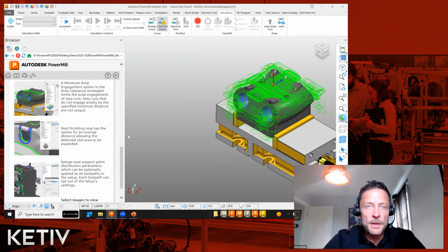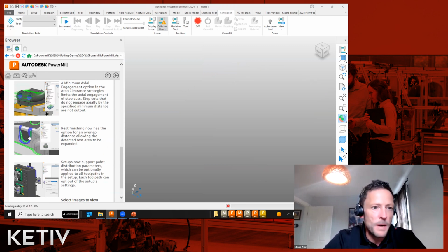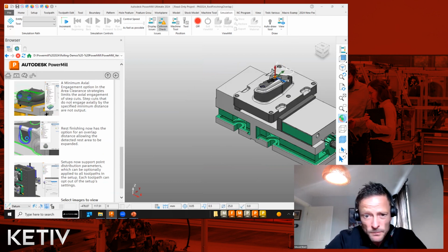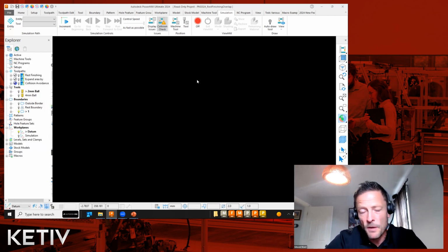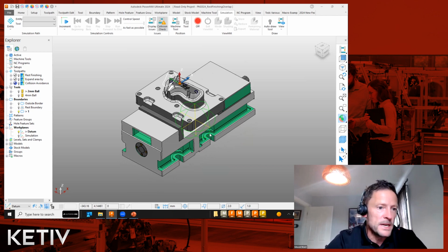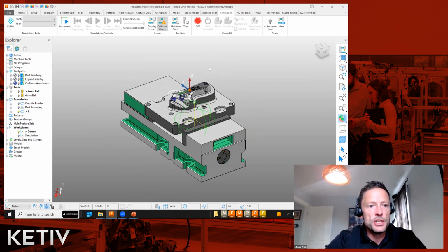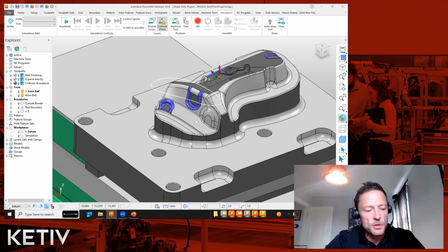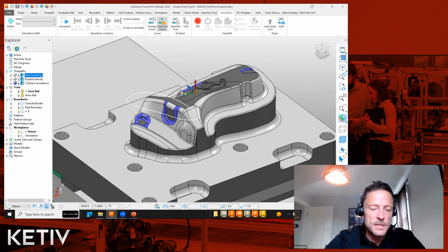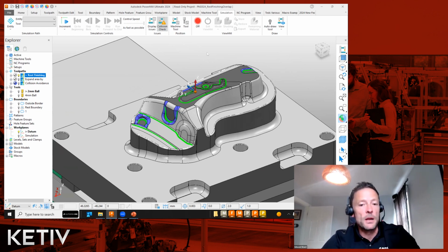Now, that overlap is very important for pure blend kind of options here. I've got a part there that's pure 3D. And then generally we would have some kind of steep toolpath, such as a constant Z toolpath, or even a steep and shallow, for example.